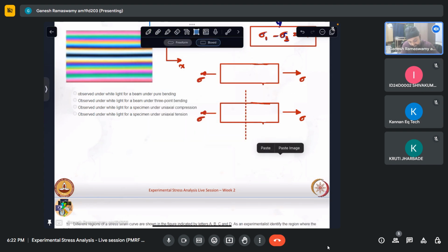Let me pass this imaginary section, and what I'll do, I'll just cut this. Now I know when there is something in uniaxial tension, if I apply equal forces on both the ends, it deforms, but it is still in equilibrium. So there has to be an equal and opposite force that is getting applied. So that force,